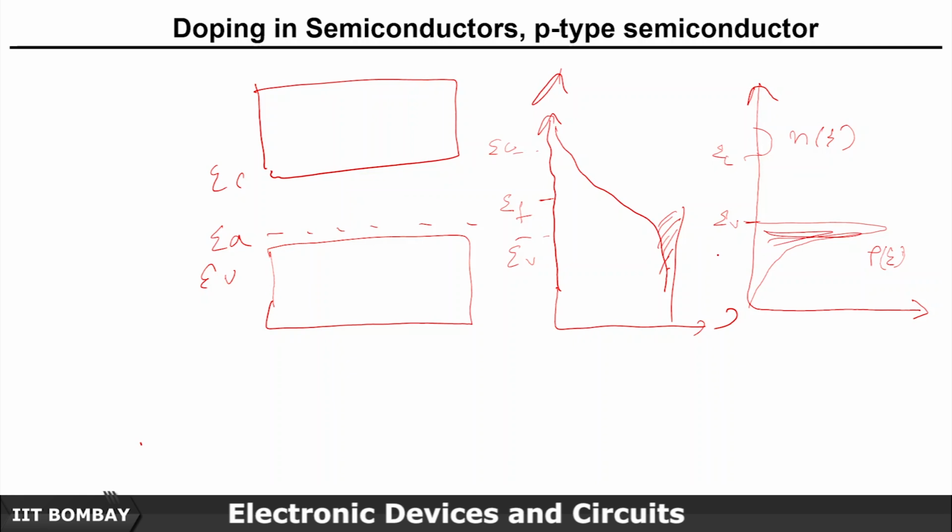So basically not much difference, except for the introduction of the acceptor levels and the donor levels, and your Fermi energy level shifts up and down. We have seen that, and this shift of the Fermi energy level will depend on your dopants or the acceptor atoms. The higher that is, the higher the shift would be. So now we will see how it looks.